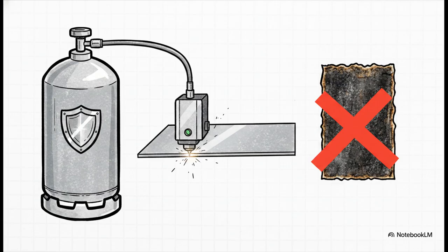It's a gas defect. It's caused by insufficient nitrogen purity, specifically anything less than 99.99% pure, or even just a tiny microscopic leak in the supplier's gas line that lets a little bit of oxygen slip in. If you are sourcing for medical or food-grade applications, your big takeaway here is to explicitly write high-purity nitrogen in your next RFQ. Don't leave it up to chance.